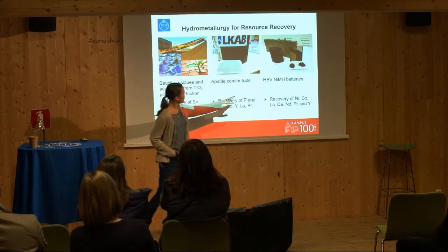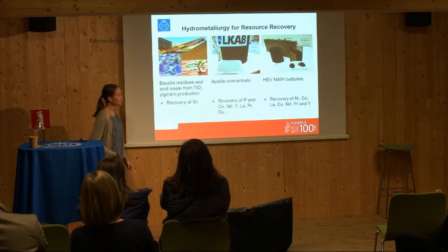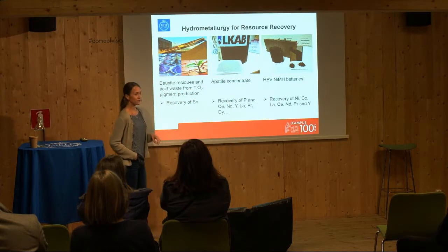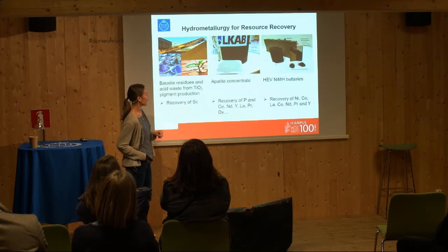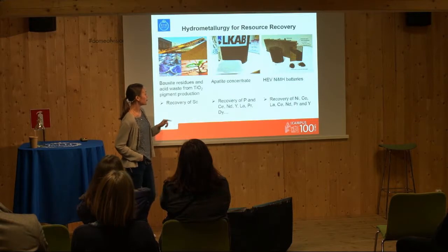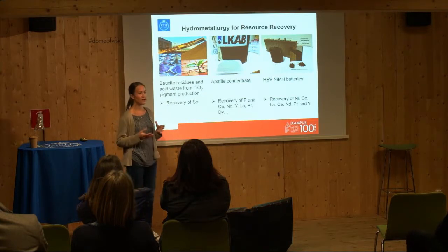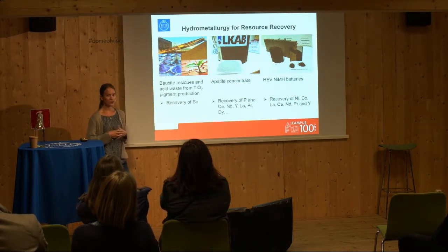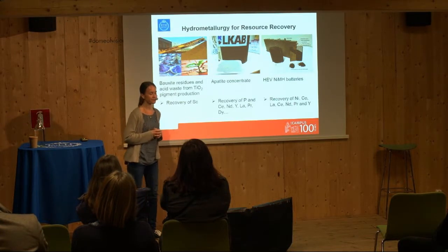And then the third project here, we are recovering the valuable elements from nickel metal hydride car batteries. And the valuable elements here are nickel and cobalt. Cobalt is also on the EU list of critical raw materials. And also a lot of the rare earth elements are in there. This is also a collaboration with IVL, the Swedish Environmental Research Institute. What we do here is that we actually dissolve the active anode and cathode materials in acids, and then we investigate different ways to combine different separation techniques to separate out the valuable elements from these waste materials.